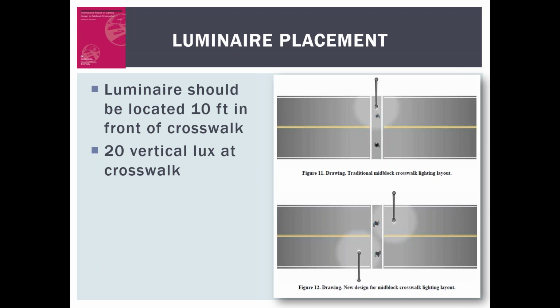Yeah, I know that in a number of our areas, the pedestrian level lights have actually been put on the back of some of the street light poles, so that they're using the same pole but having a tall light going out over the street with a mast arm, and then a shorter light over the sidewalk area. The pedestrian level lights are typically further back from the roadway, so that's not as big of an issue for run-off-the-road drivers. In addition, they're typically more often used in lower speed areas, the downtown areas. It's not that much of an issue for motorists running off the road or hitting them or creating extra obstacles for motorists.